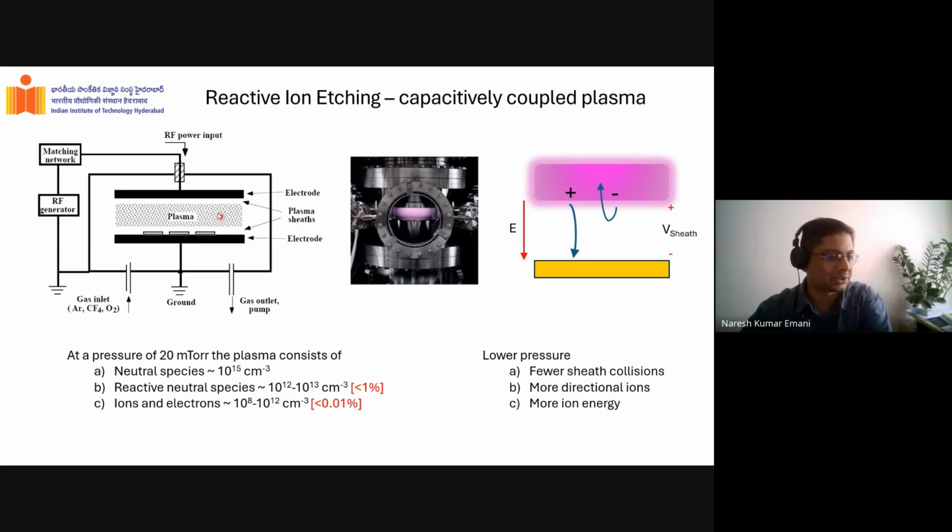You essentially create this plasma in between the electrodes. All right. Now, this plasma is not a simple plasma. Typically, you go to what we call millitorrs, one of the units of measuring pressure. 760 torr is atmosphere, right? So millitorr is very, very high vacuum, medium vacuum, let's say, not high vacuum, medium vacuum. You have 20 millitorr, or this is roughly 2 pascals or something like that.